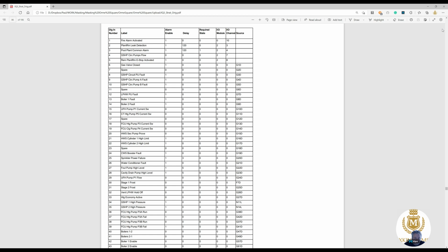Plant room emergency stop, I need to take that. Well, I'm going to leave it there, but actually I'll take it across the Trend network back to the MAC36 controller. So I'll just put DI5 network, and then I can take across 8, 9 and 10, the ground source heat pumps PU.